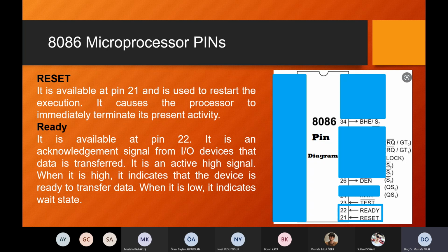There is one other control signal that is involved with the memory and input-output interface. This is the ready signal. It can be used to insert wait states into the bus cycle such that it is extended by a number of clock periods. This signal is provided by way of an external clock generator device and can be supplied by the memory or I/O subsystem to signal the 8086 when they are ready to permit the data transfer to be completed.